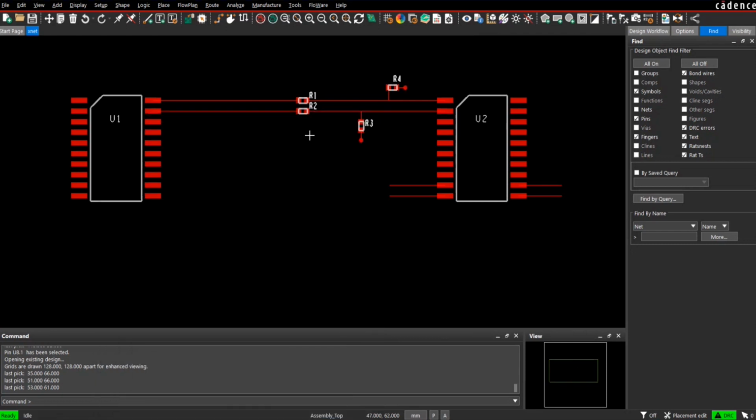And this makes perfect sense, as mentioned. When you want to constrain these kind of things, then you have to constrain, for example, the flight time from this driver to this receiver and not a flight time through a complete ground net or something. This is useless. So this is the first thing here.